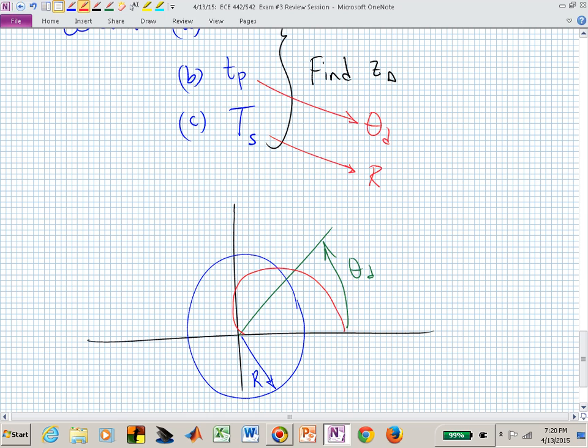More damping is you're collapsing those hearts, those logarithmic spirals, down until you get to the real line. Then you don't have underdamped, you have these decaying exponentials. So now if you need a certain percent overshoot or less, which side of the heart are you going to be? Inside or outside? Inside. You want to be collapsing towards the real line. Is that clear?